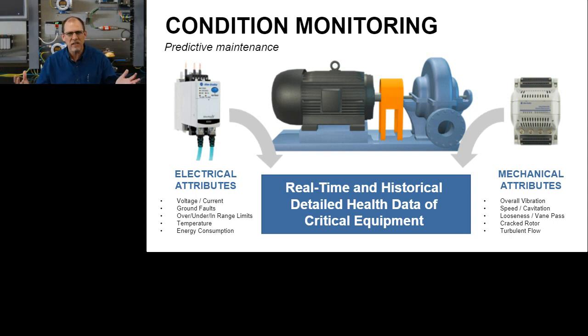You can see things like cracked rotors or turbulent flow. That was another thing that we looked for, what we called departure from nucleate boiling. It was something where if you could detect bubbles forming in the fluid that we were pumping, that your efficiency was really dropping, and things were going on that you didn't want, so you could react to them.